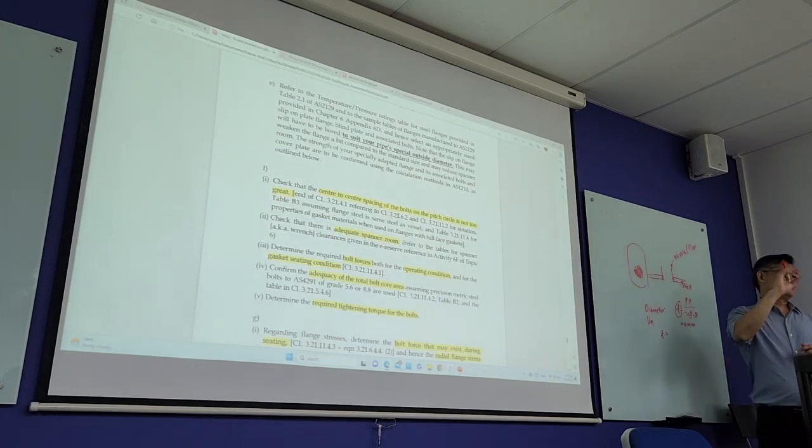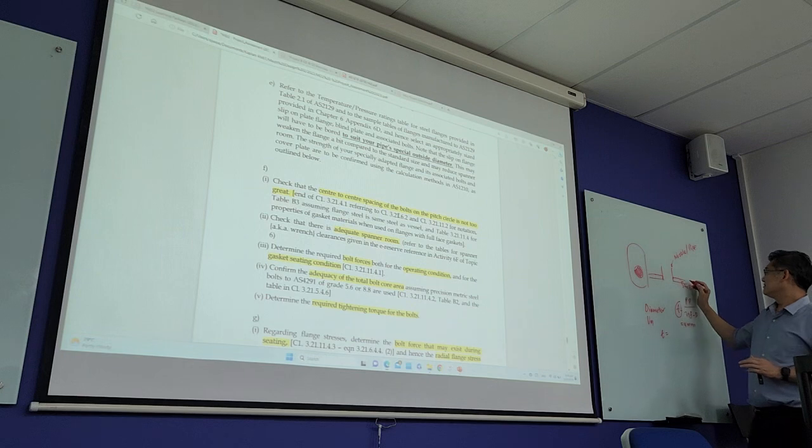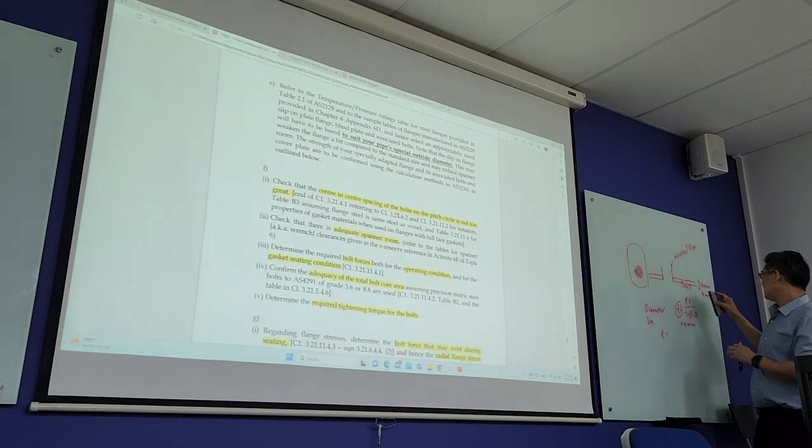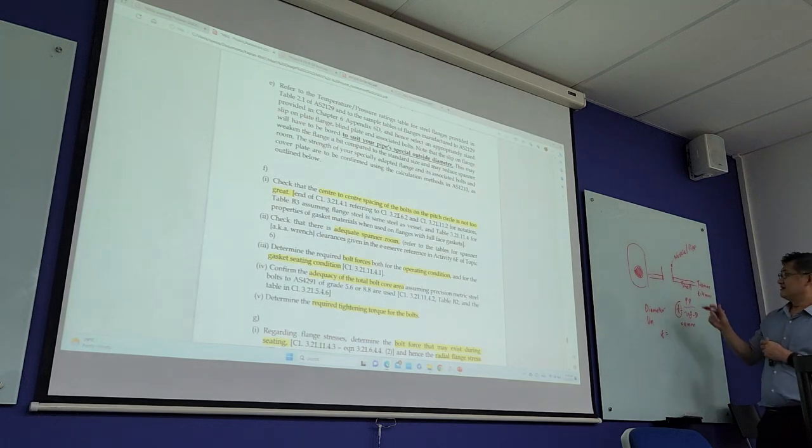You go to the catalog, you don't find 4 mm. Let's say the catalog shows 10 mm, which means our shell here is 10 mm. But your T that can withstand the pressure is 4 mm. So they represent it with the capital T, and this is small t. What happens is this area that we cut away, over here, can be compensated by the area here.